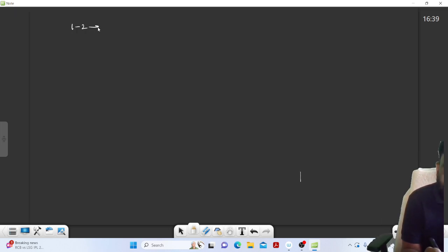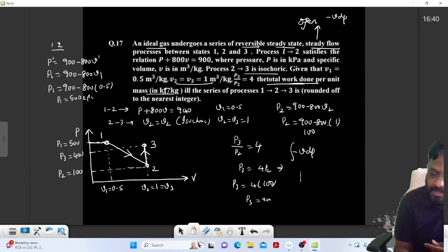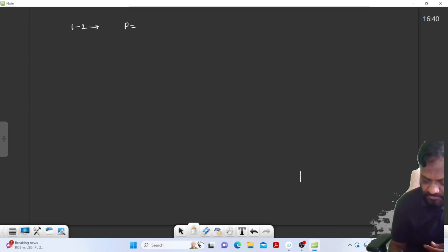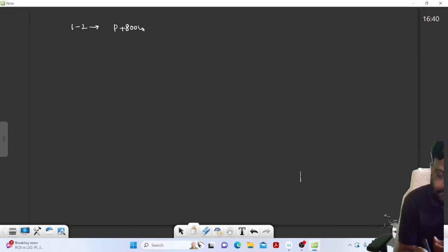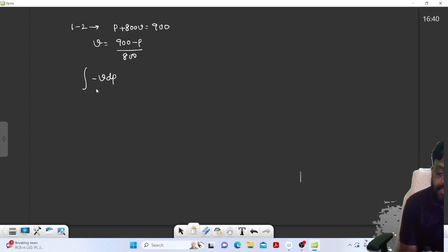For the 1 to 2 process, what is the equation? P plus 800 V is 900, or P is 900 minus 800 V. For the 1 to 2 process, it is P plus 800 V is 900. What is V? V is (900 minus P) by 800. Correct? So minus VdP, and pressure is in the 1 to 2 range.